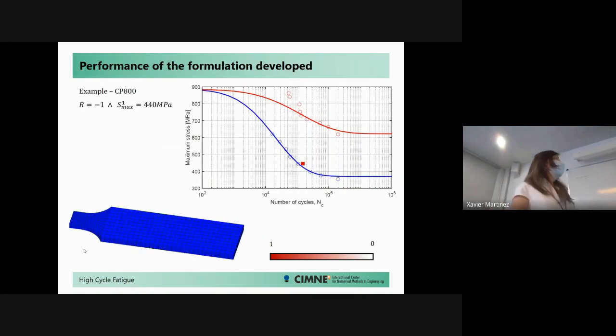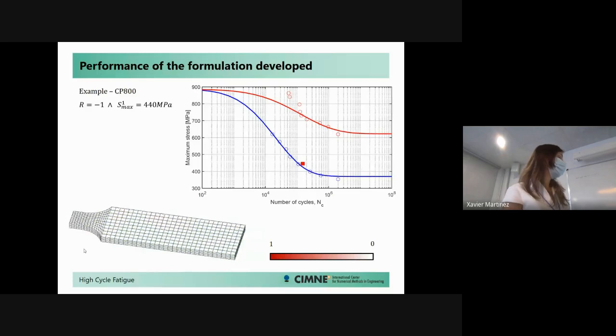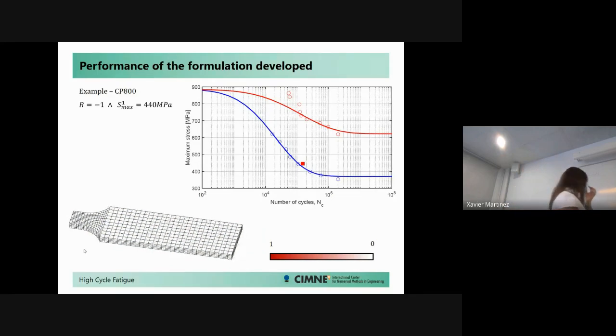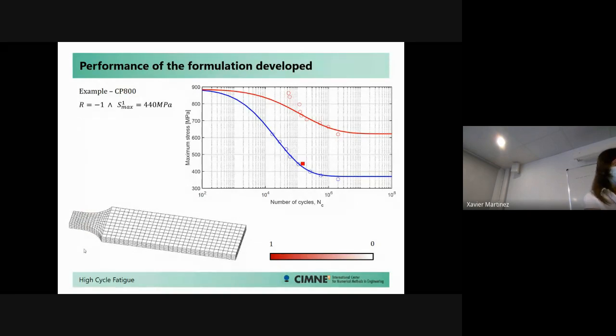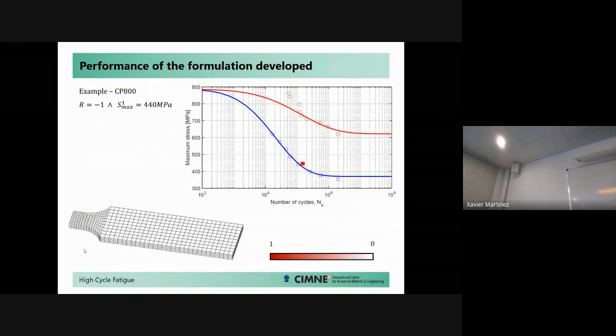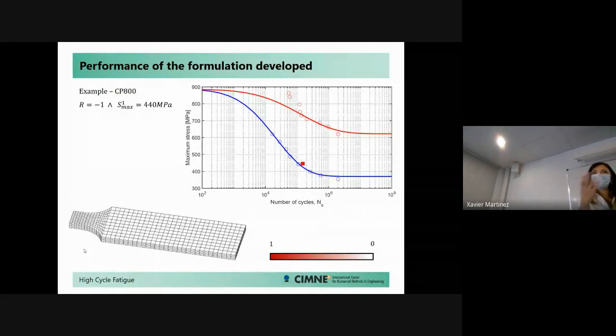Okay. Now let's take a look at some examples for different types of steel and what I can see, for instance, in a numerical simulation. I will be able to follow the initiation of damage and, most importantly, the propagation of damage throughout the geometry. This is what you cannot do with the commercial solution, okay? Then I will obtain, of course, from the simulation a specific number of cycles at which my sample has completely failed because the damage has propagated throughout the entire cross-section.